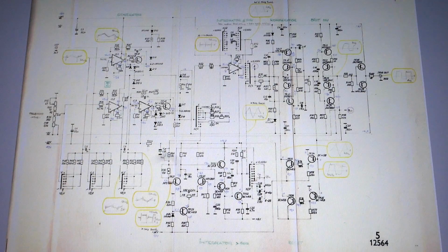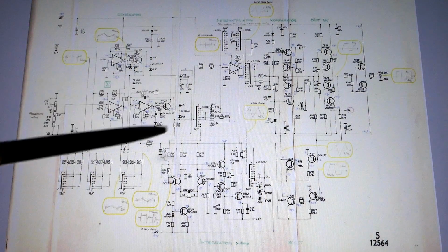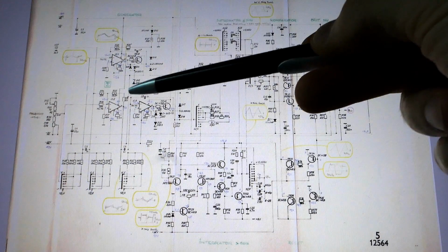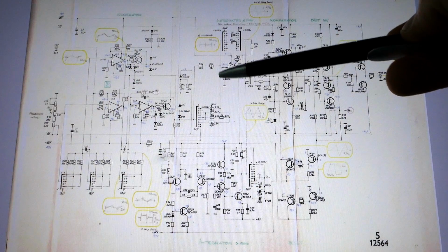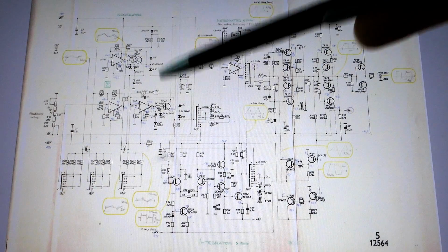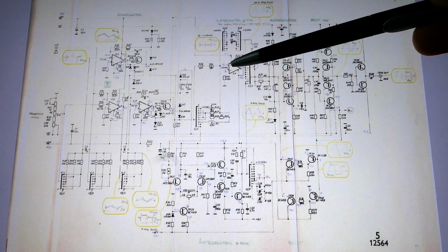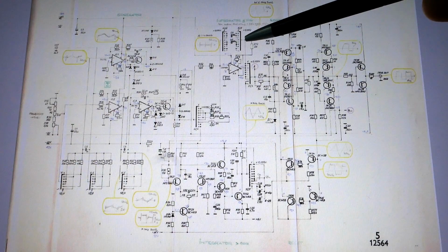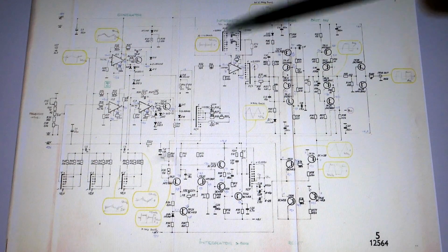And there is this weird voltage-controlled frequency thing with the op-amps and 2 transistors and a lot of diodes. And the frequency can be controlled using the potentiometer or the voltage-controlled frequency input. I will go back to this insanity later. And from this insanity it goes into this integrator, which is using the metal can op-amp. And basically the signal goes via resistors into the inverting input of it, and there is a negative feedback from its output through a capacitor into its inverting input.